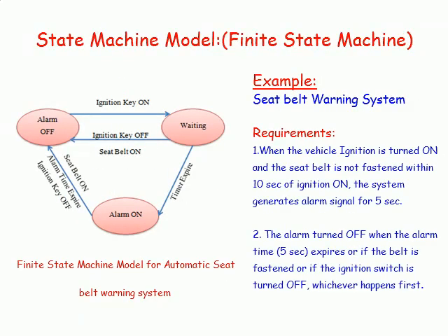And the third model is the state machine model, which is used for modeling reactive or event-driven embedded systems whose processing behavior is dependent on state transitions. Embedded systems used in control and industrial applications are typical examples of event-driven systems. The state machine model describes the system behavior with states, events, actions, and transitions.